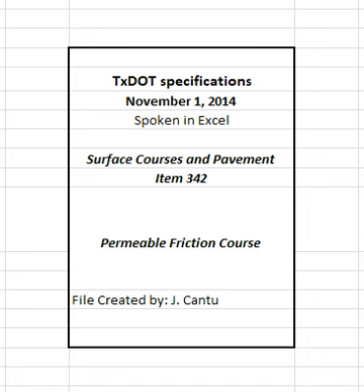The engineer may also obtain independent samples. If obtaining an independent asphalt binder sample, the engineer will split a sample of the asphalt binder with the contractor. The engineer will test at least one asphalt binder sample per project to verify compliance with Item 300, Asphalts, Oils, and Emulsions.